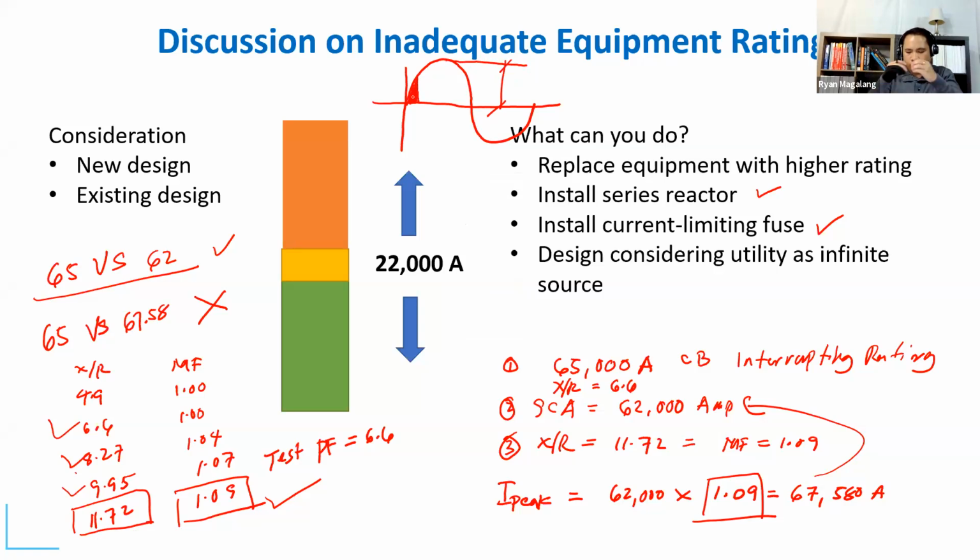The fuse element is already severed, and besides that, the arc is quenched, because that material offers a very high magnitude of resistance, and instead of being able to go to the peak, now you are here. So it greatly reduces the amount of fault current that it allows to pass through.